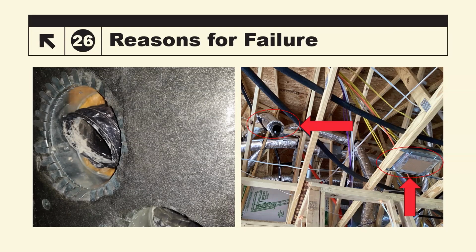And then the one on the right, I know this happens. It's a common thing. The installer ran out of the specific duct size that needs to be fixed to the boot that you see in the lower right-hand corner. He didn't have it, so they're just going to assume that someone else will come back and fix it. But showing up to a house to do a duct test and finding this, especially after you've spent an hour trying to duct test it, and now suddenly you find this hanging up in the attic, it's kind of frustrating.